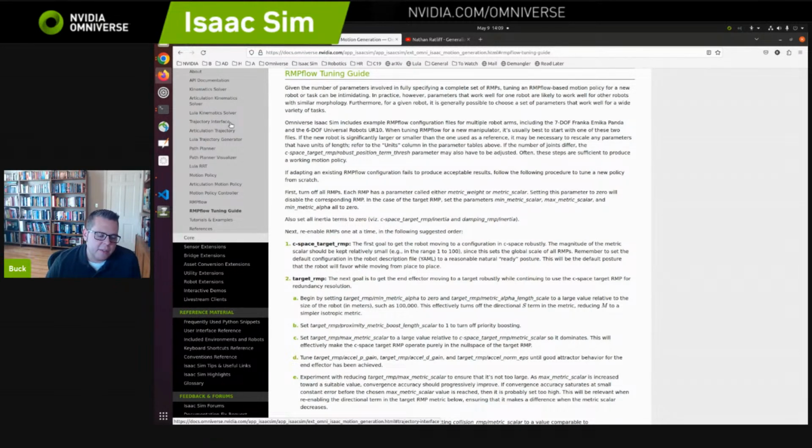So we do have an interface for building up a path out of a series of moves like this, and then automatically computing a time optimal trajectory given a set of acceleration limits, velocity limits, and jerk limits. It'll produce a time optimal trajectory with smooth velocity, continuous acceleration, and bounded jerk.